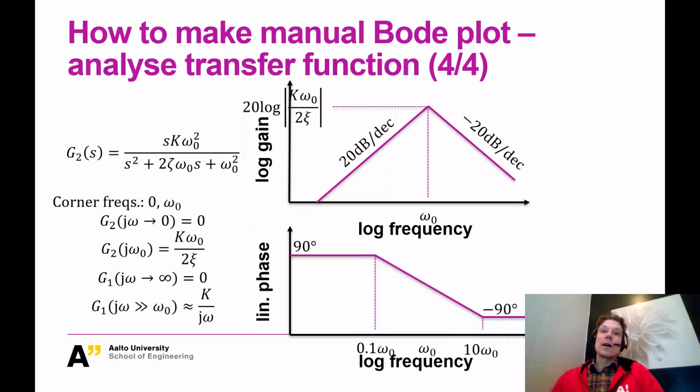So then let's say you want to make a bandpass filter, for instance. Then you actually have to make the numerator some larger order than zeroth order. In this case you have made a first order numerator and second order denominator. And this means that your gain will be increasing.